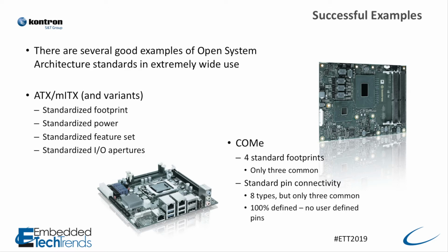In COM-E, there are 4 standard footprints, although 3 are the most common. And then there's standard connectivity. There are 8 different types defined by the standard, but really only 3 are common, and there are 3 that are aligned along certain product needs, certain industry needs. One of the key things about COM-E, though, is that there are no user-defined pins. Everything is defined on the connectors.